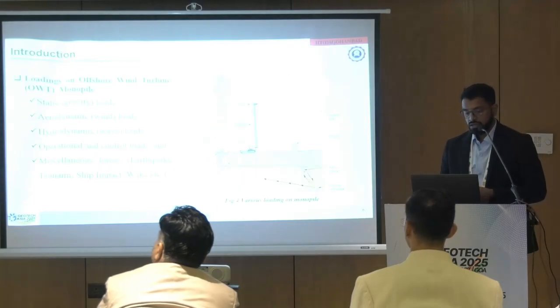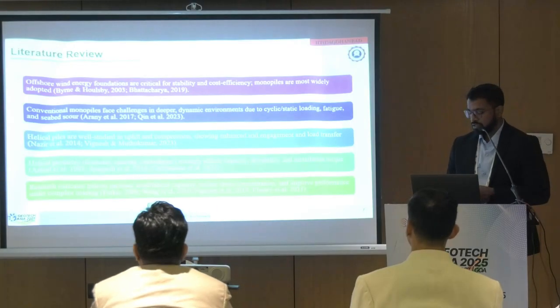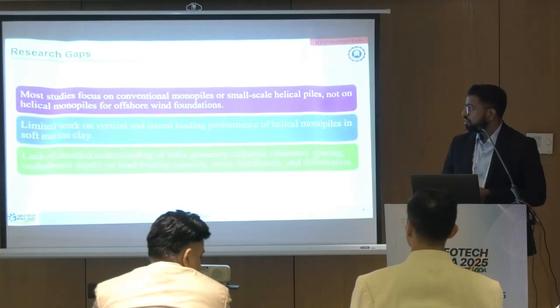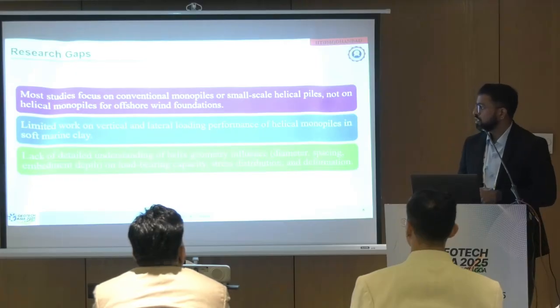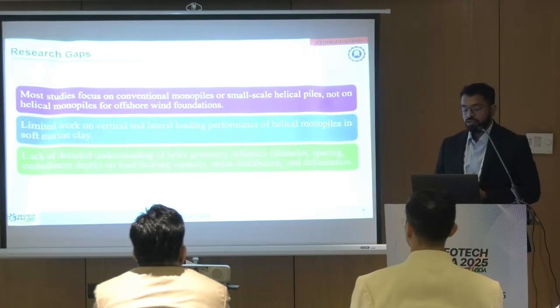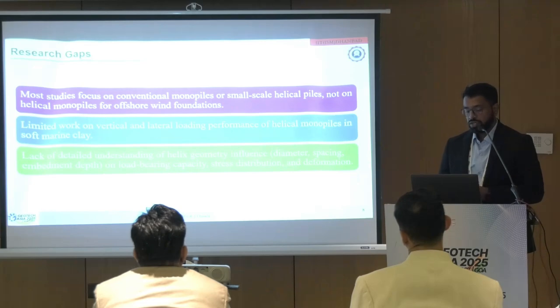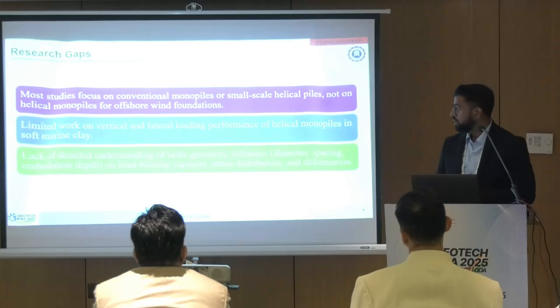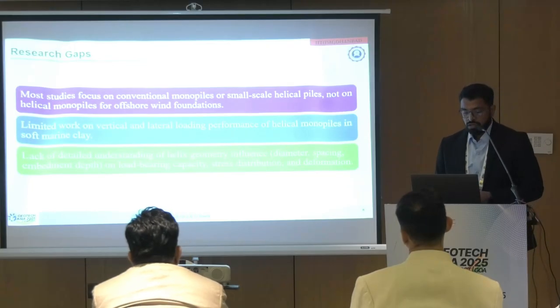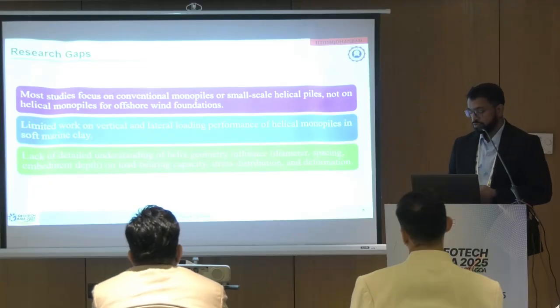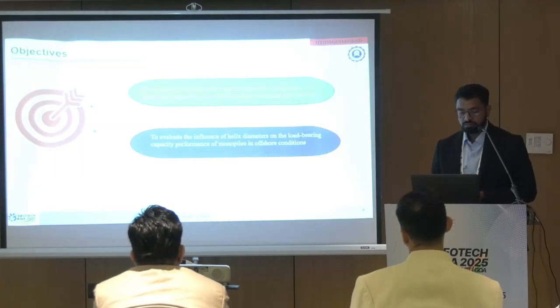Based on previous literature reviews, we have a few research gaps. Most studies focus on conventional monopiles or small-scale helical piles, not on helical monopile offshore wind foundations. Further, there is limited work on vertical and lateral loading in soft marine clay, and a lack of detailed understanding of the influence of helix geometry on load bearing capacity, stress distribution, and deformation.